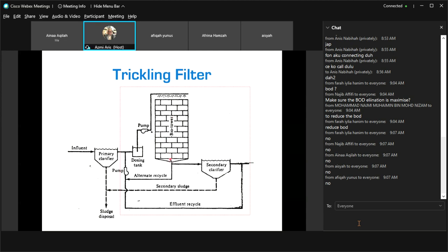The wastewater flows through the media by gravity, so you don't have any control on the hydraulic retention time. The concept is that the higher the media, the better the contact between the wastewater and the microorganisms, or the biofilm. If you have 2 meters, the contact is only within that 2 meters. But it's very difficult for you to tell the time because it depends on the gravity flow of the wastewater.